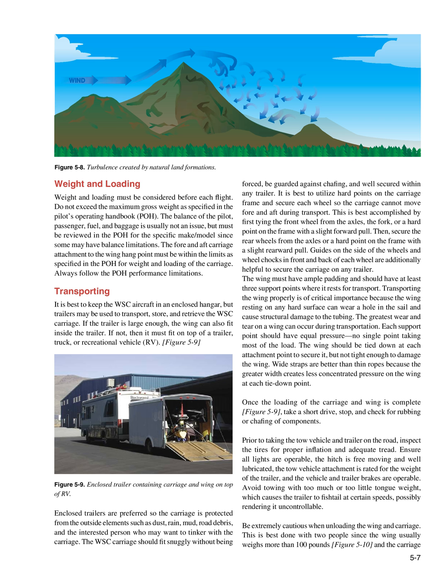Weight and loading must be considered before each flight. Do not exceed the maximum gross weight as specified in the Pilot's Operating Handbook, POH. The balance of the pilot, passenger, fuel, and baggage is usually not an issue, but must be reviewed in the POH for the specific make/model since some may have balance limitations.